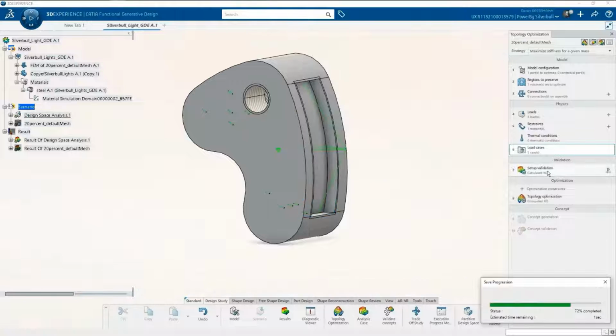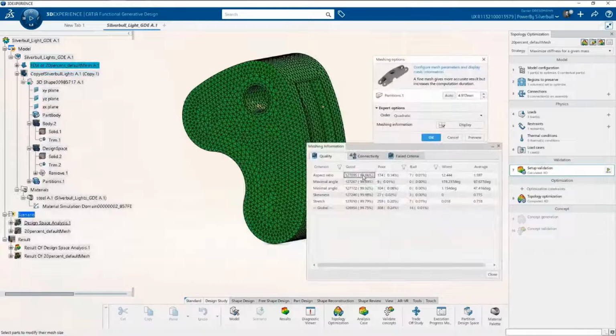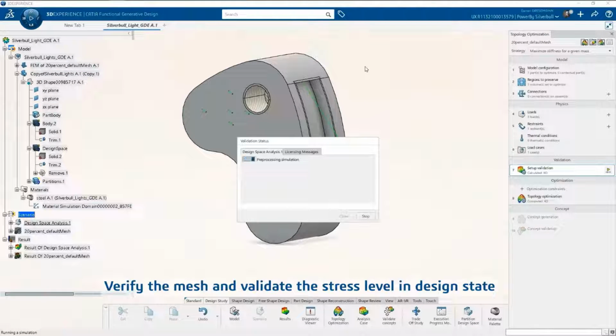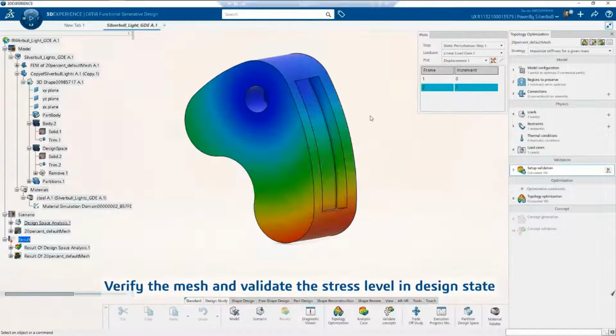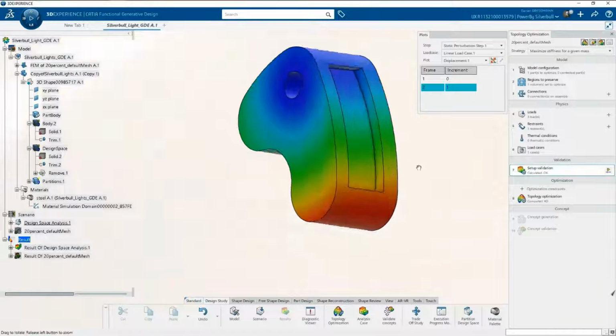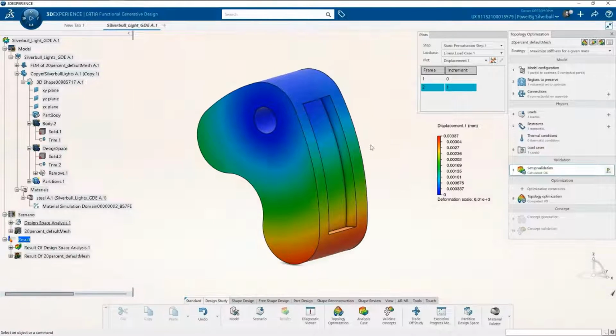Furthermore, the user needs to apply the forces on the model and the load cases, of course. And then he can run and validate the status of the stresses, the displacements, and everything like that. So these are our entry point for the simulation in this case.